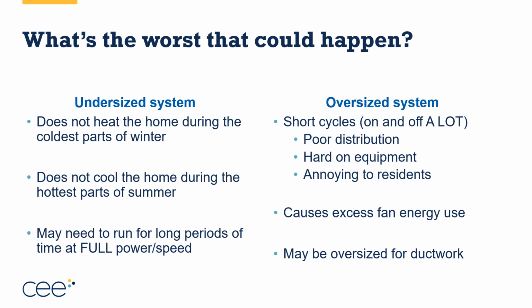The second thing is about when this changeover happened. I believe it was 2017 is when they were no longer allowed to be made. This is because the federal appliance standards that the DOE and some other federal agencies help manage went live in 2017, and essentially distributors had until 2019 to sell off any of the equipment that had been already under construction. So effectively, if you bought a piece of equipment anytime from 2019 and later, a central air handler system should have an ECM motor or ECM fan as a component of it.